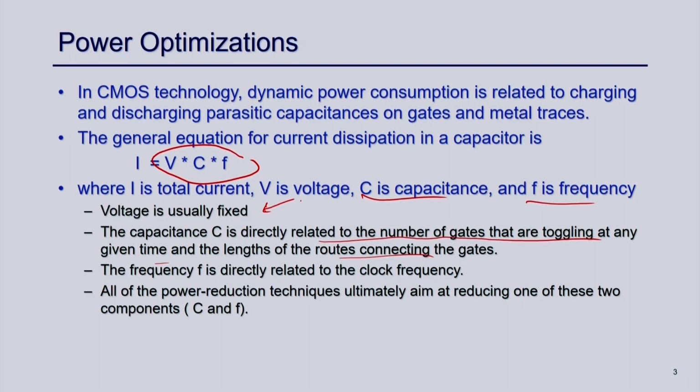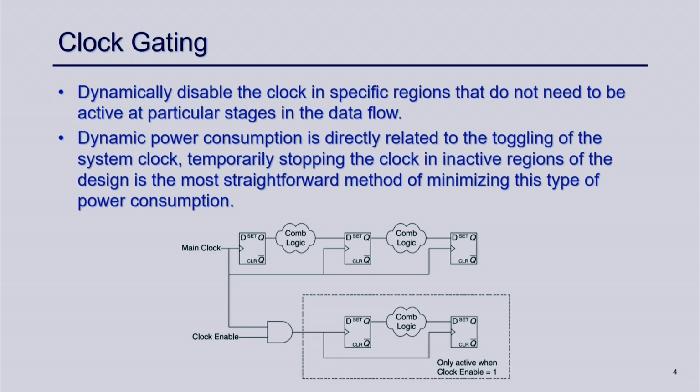Okay. So, let us move on. Some of the well known techniques applied in digital design, and the most well known is clock gating. What is clock gating? In your design you try to switch off some portion of the circuit which is not active at the current moment of time. It is obvious that in a big design, not every part of the circuit is doing actual computation in all the clocks.